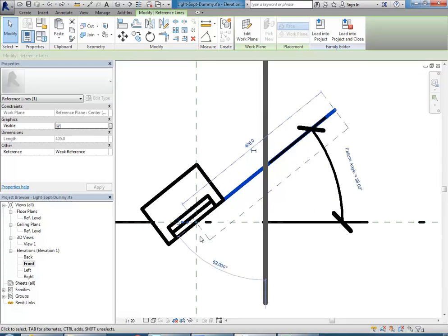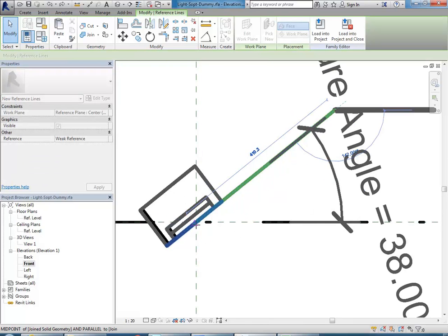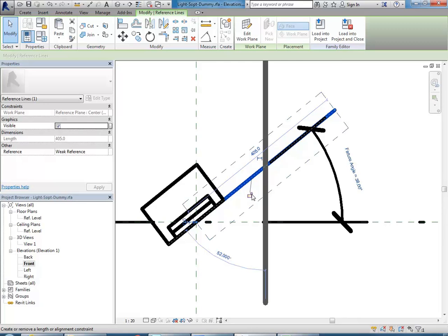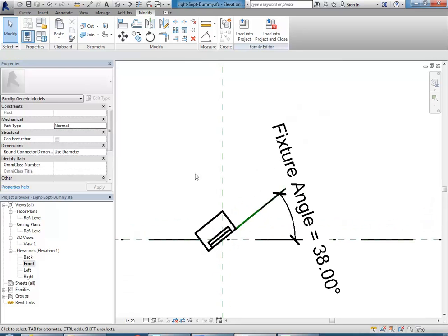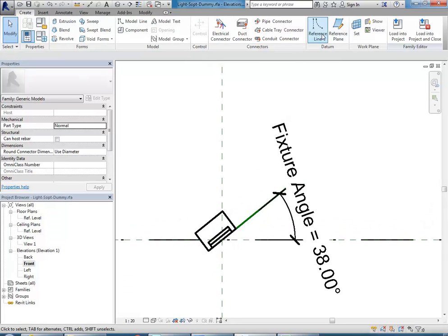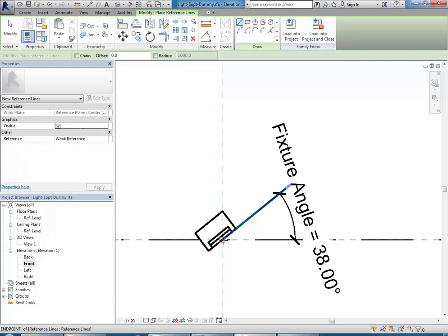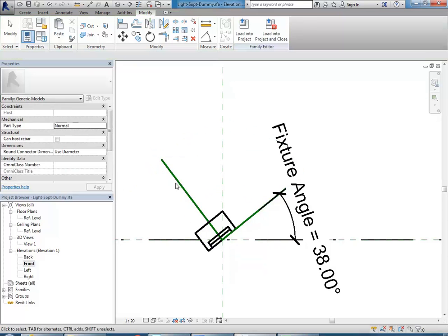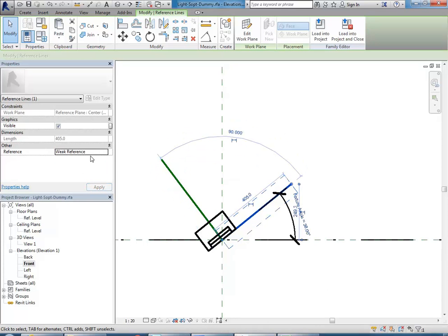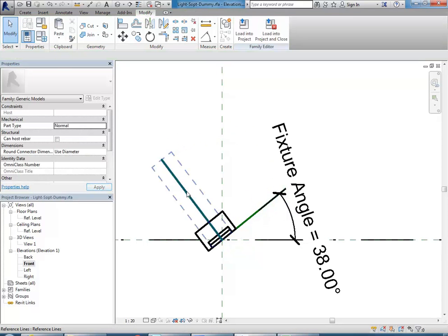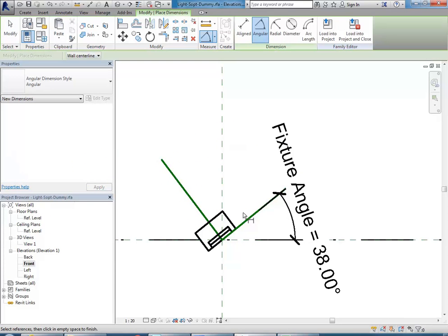Okay, so I'm going to have to try and get that plane locked somehow. Otherwise we'll have to do the plus 90, so drawing another reference plane or reference line perpendicular to that. Somehow seems to make it do a better job, and not a reference. Okay, so drawing an angle from there, sorry, from here to here.